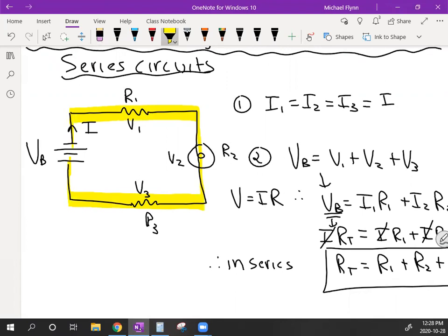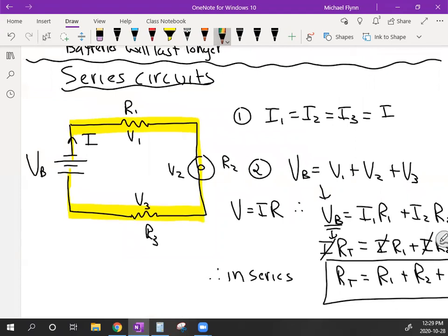First resistor, I call it R1. The light bulb, I'm calling R2. So a light bulb, any load can be considered a resistor. Okay, it's just that some loads have special symbols. So the light bulb is an example of that. And the third resistor, call it R3. Okay, so that is a letter R down there, R3. Now, the thing we know, what do we know about a series circuit? Well, since there's only one path, the current must be the same.